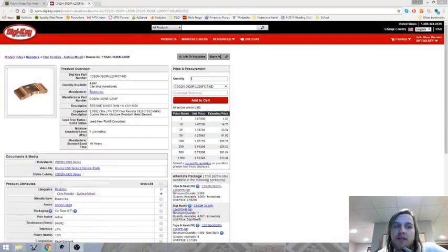Something like an Atmel chip, which is on the Arduino, has a typical ADC range from 0 to positive 5 volts. As an example, I'm making a circuit that uses this current sensing resistor, which is a very low resistance and a high wattage. That means it's good to have a lot of current going through it, and there won't be a lot of power loss through it. It's also reasonably high accuracy. But since this is such a small resistance, we know from Ohm's law that the voltage across this resistor is going to be reasonably small. So we need to make sure that we utilize our full ADC range.